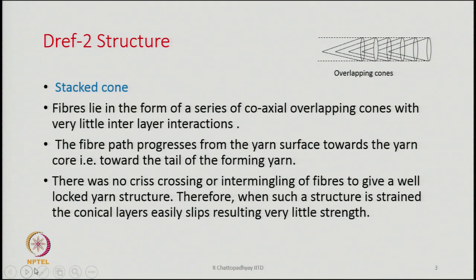Now, we will discuss the structure of both the yarns, DREF 2 and DREF 3. The DREF 2 structure, as I said earlier, is basically based on the open end spinning principle, because there is no core filament or core fibers we are introducing. There is only one drafting unit where fibers are opened out by the opening rollers, and then they are released on the friction drum.